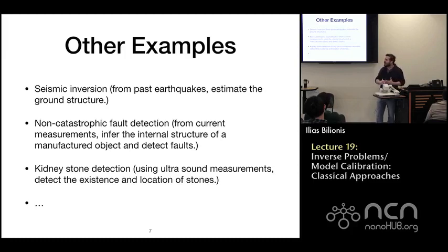If there is a defect, what should happen is that the electric conductivity should change wherever that defect is. So that defect should change what you would ideally measure if you didn't have the defect. So based on the sensor measurements, you want to go back and characterize the electrical conductivity, say, of that component, if it is a metal, and you will see the defect.